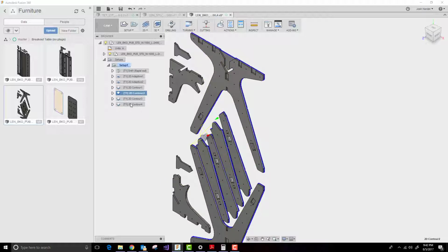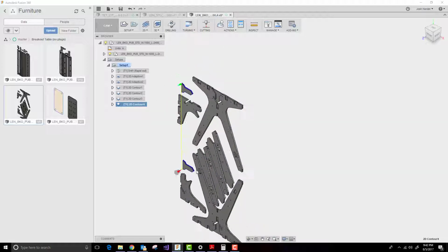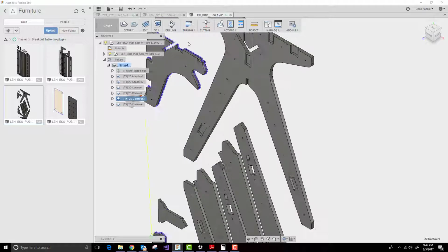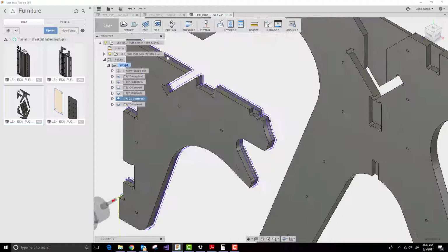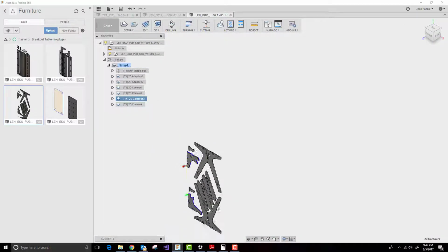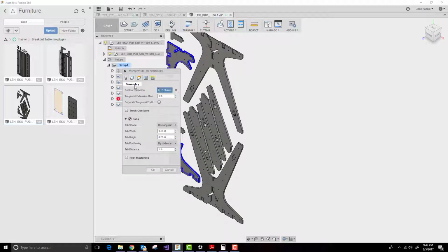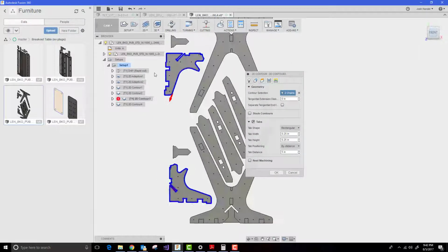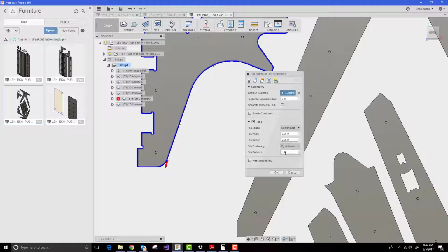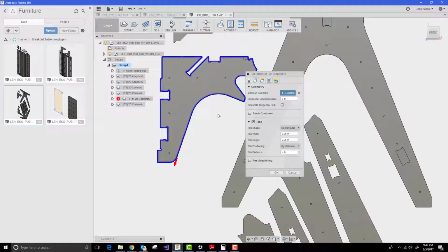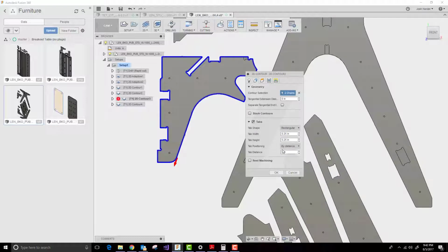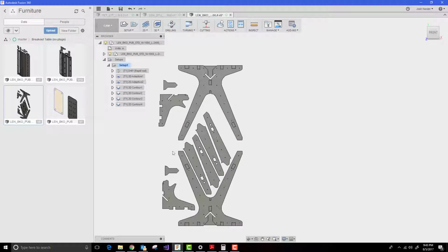And then I started cutting out the parts, and more parts, and then finish cutting out the parts. It really is straightforward. Obviously, when I'm cutting the parts, you notice there are hold downs. I don't know why, but I don't like the default hold down locations most of the time. So when I do geometry, I must have done it by side. I play with this a lot. Whenever you're sitting here wondering, is that the right spot for those? You play with it and get it right. Half the time I end up, instead of going by distance, going by point, and literally putting in the points that I want. So that's what I do there.